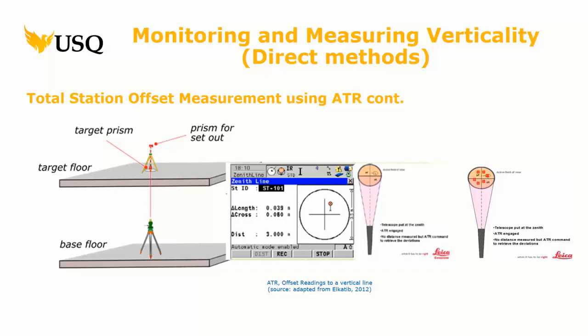Right? So this is an example, really simple to do. I could see some of you would actually get in a situation where you think, okay, that's vertically. Why can't I do that horizontally? In other words, if I can download that data, if I'm doing precision work, say in a tunnel, why not record how far it's out from that particular prism mark, right? Because you can do it in reverse as well.